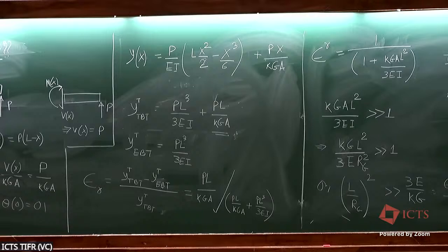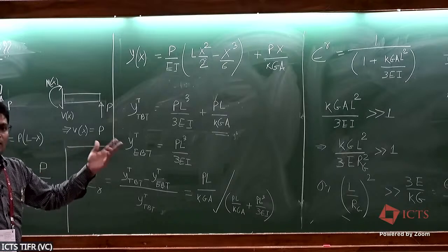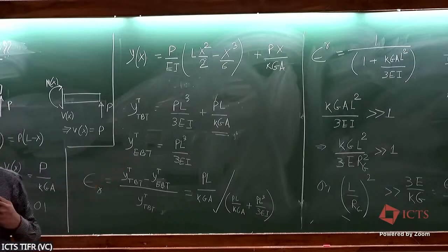Oh, okay, yeah. Yes, from a designer's perspective, because it is giving you higher deflection, so you should design using TBT. Is that what you're saying? It is anyway more accurate. So it also depends on the designer. At the end of the design, they always have some factor of safety. So even if they work with Euler-Bernoulli beam theory, they will say, let us have some factor of safety to account for the modeling error.